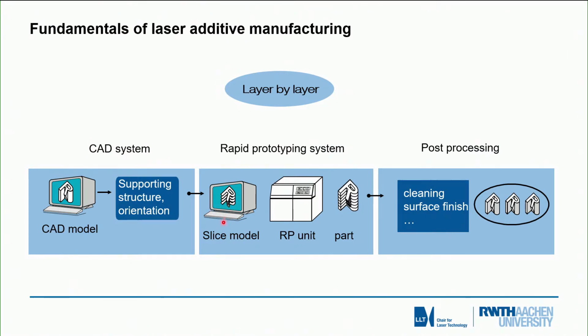This is more or less the inverse of what you may know from a computer tomograph, where you have a 3D picture and slice the information to look at individual cross-sections. So similar technology here. By using the sliced data of the individual layers, we then can print the part layer by layer and come up with the 3D reconstructed image that we designed in the first place.